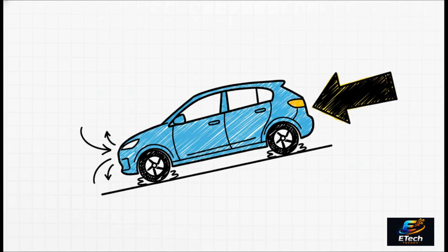Let's break those down really quickly. First, the motor has to overcome rolling resistance, which is basically just the friction of the tires against the track. Second, aerodynamic drag. That's the literal wall of air pressure hitting the front of the vehicle as you speed up. Third is gradient resistance, which kicks in based on the slope or elevating angle of the road. And finally, acceleration force, which is the sheer physical force defined by Newton's second law required to get that heavy